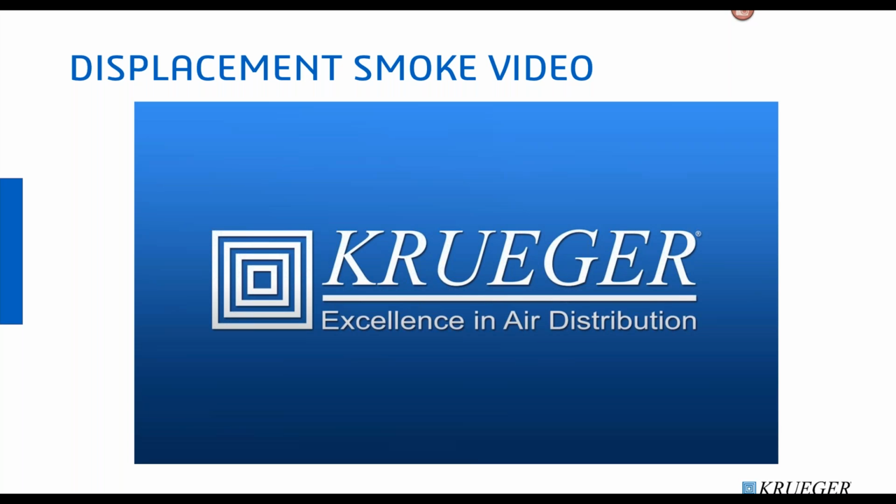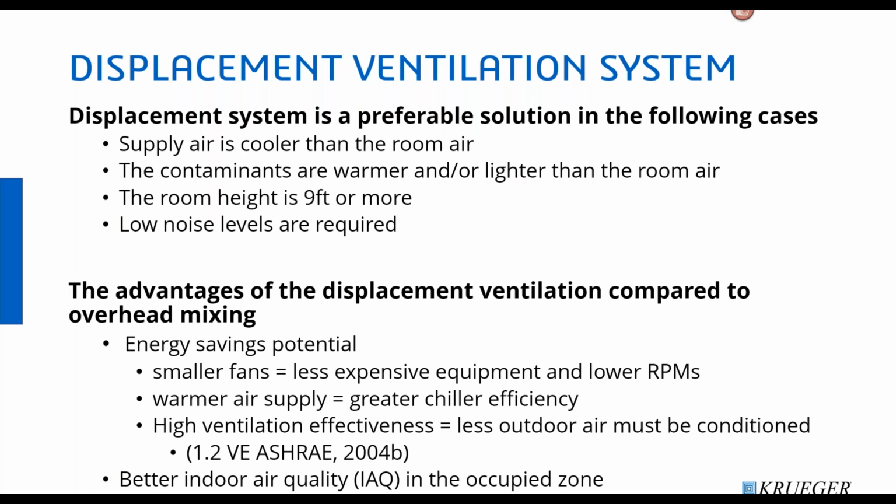Welding, for example, is a unique application where displacement is advantageous because it does help to ventilate the space more effectively. So it'll carry some of those fumes and that smokiness out of the way more effectively than a traditional overhead introduction of high mixing air would.